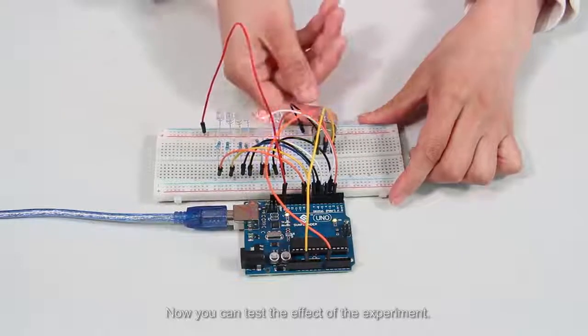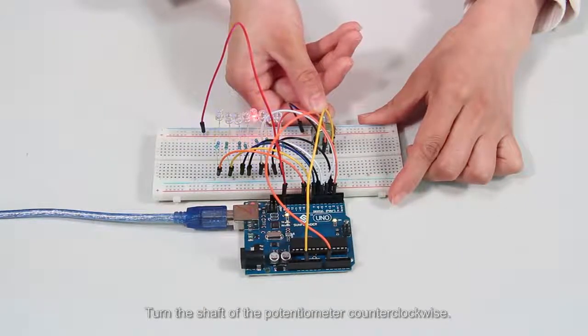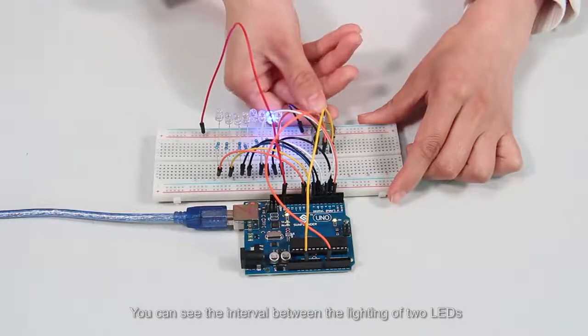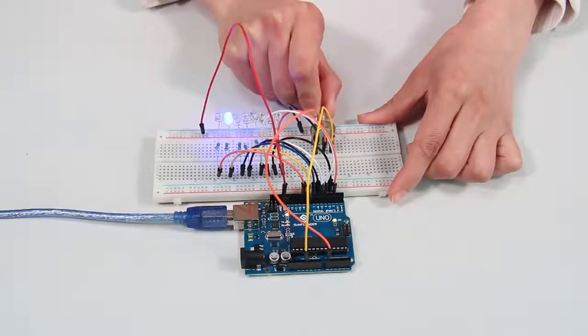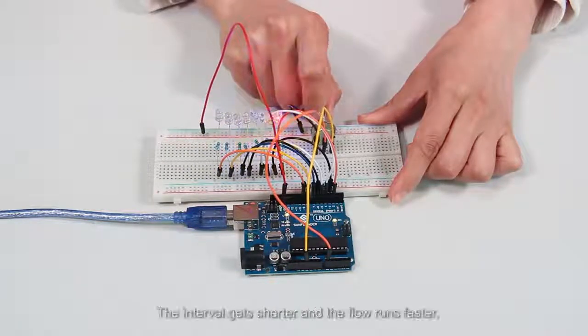Now you can test the effect of the experiment. Turn the shaft of the potentiometer counterclockwise. You can see the interval between the lighting of two LEDs is prolonged, and the flow runs slower. Turn the shaft clockwise. The interval gets shorter and the flow runs faster.